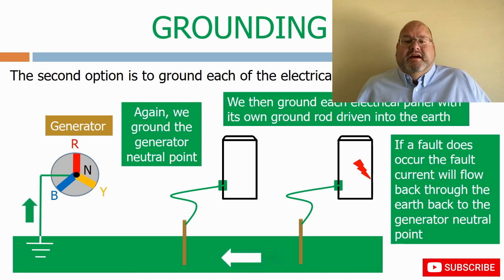The direct cable connection method tends to be used when the site is located near to the generator. Once the distance increases, the cost of the grounding cable can be excessive, and the individual equipment grounding system tends to be used. Both methodologies are fine and provide a defined path for any fault currents. We also see a combination of both systems on site, which is acceptable as long as they are tied together to provide one grounding system.